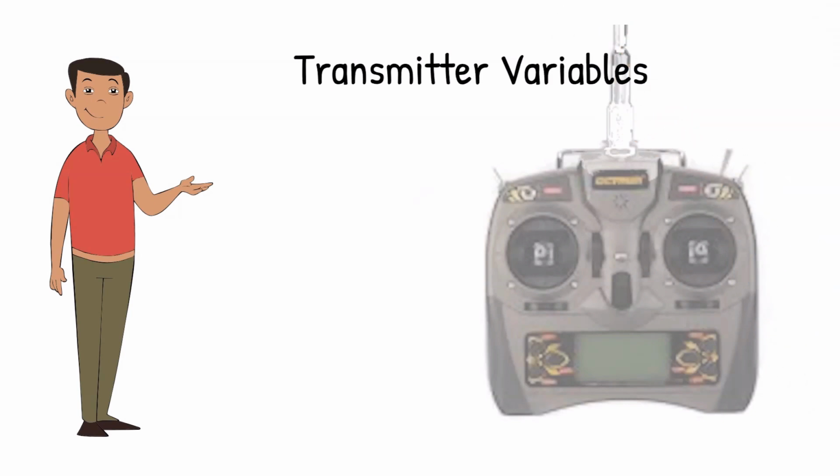First, you'll want to select the type of model it is and give it a name. Select the choice that corresponds with an airplane versus a helicopter or drone. Most transmitters will also have you select the type of wing the model has. This usually includes specifying the number of aileron servos and if the wing includes flaps.